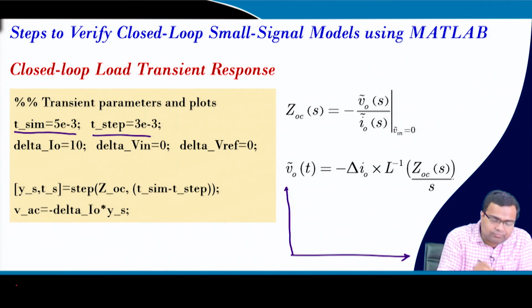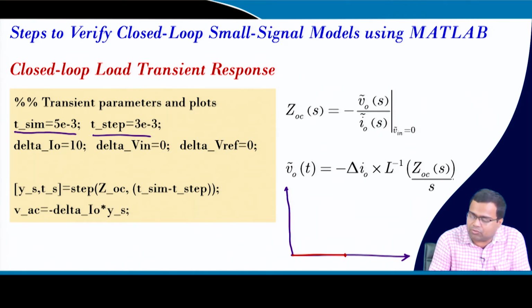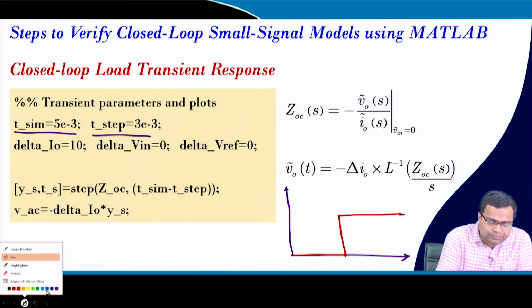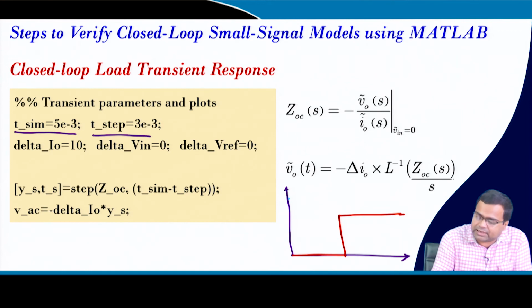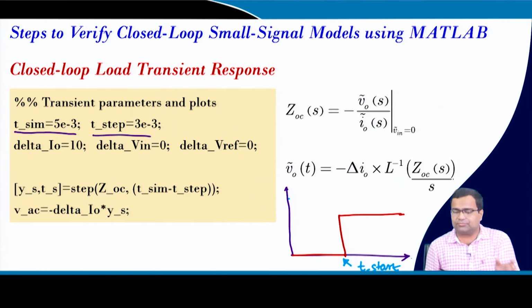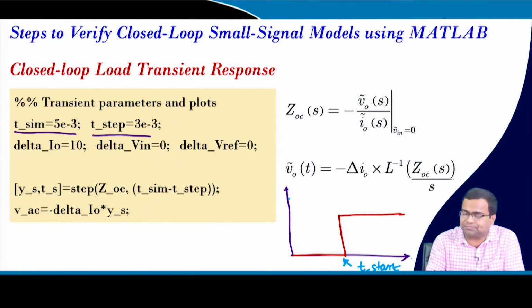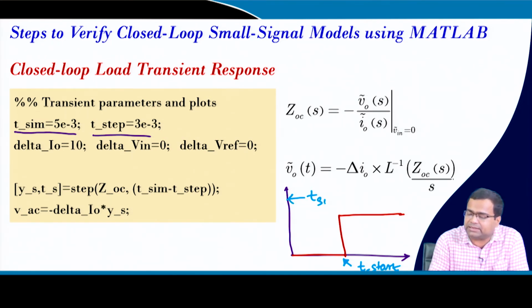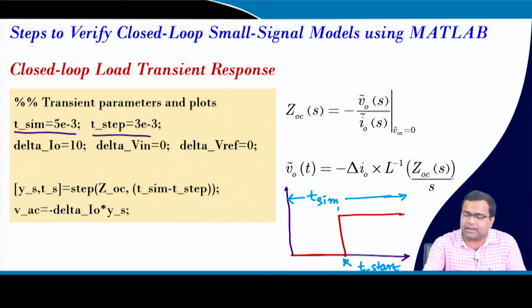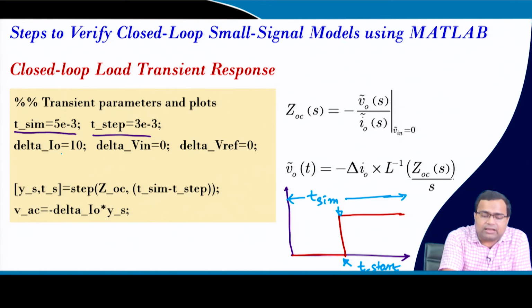Now, I am applying a load step transient here. This time this is my T start, the starting value where the actual step is applied, and this time is my T sim, the total simulation time. So, here we have applied a load step transient, and here I am applying the 10 ampere load step, no step for the input voltage and the reference voltage.